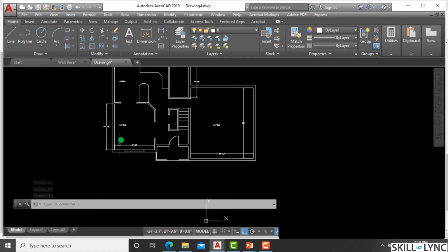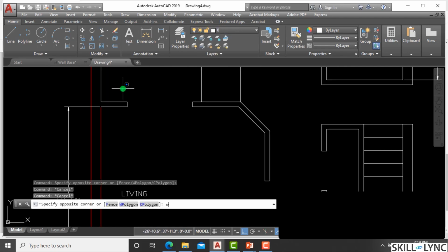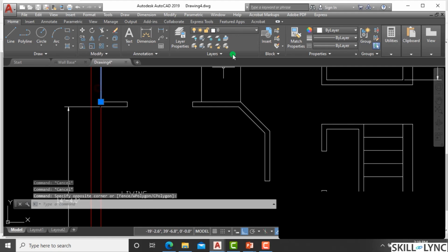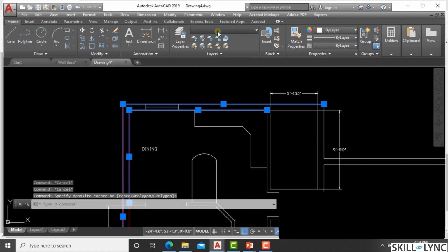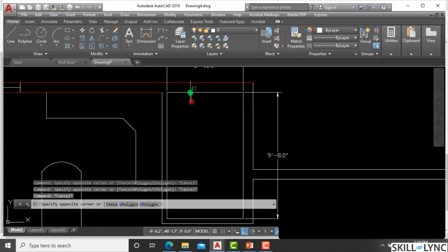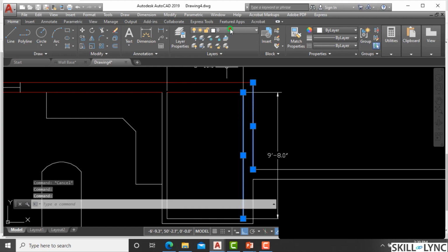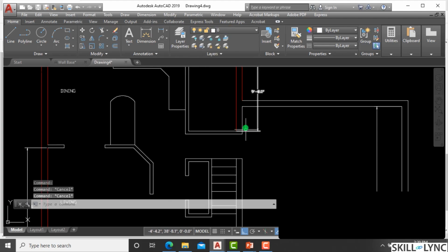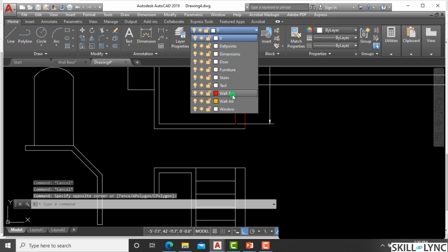Now how do you transfer these objects? Let's say you pull this line and say I want to put it in the exterior layer. You pull this line, so this object is in the wall exterior layer. So keep on selecting, and see that now the layers are set, so this is the wall for the exterior layer. I think if you do this exercise, you will understand very significantly the standard use for the layers.